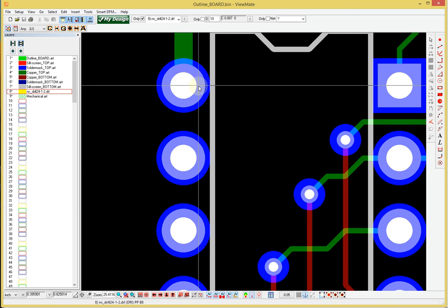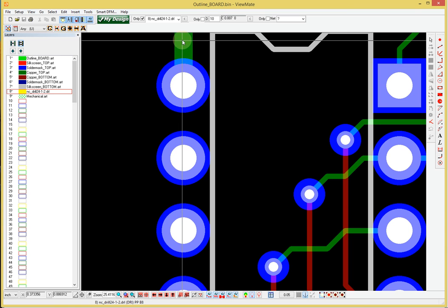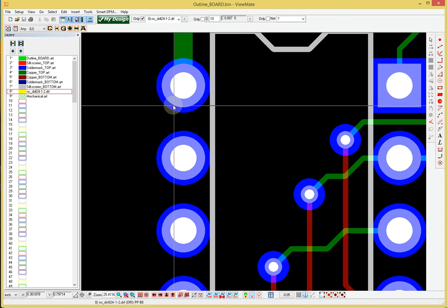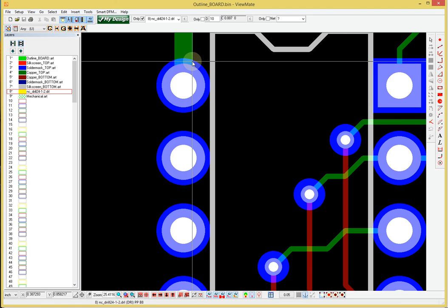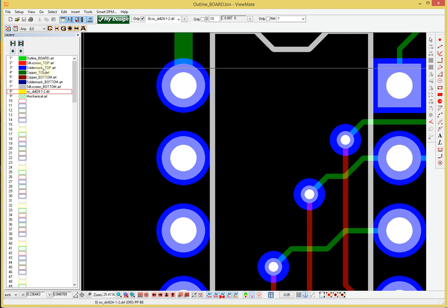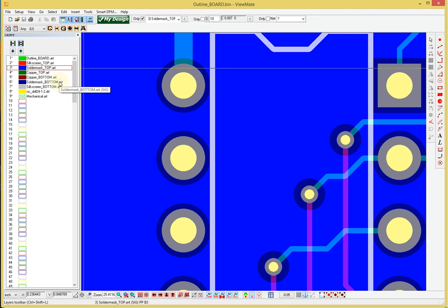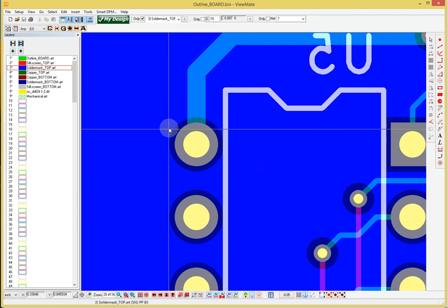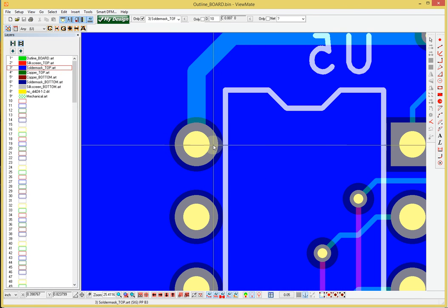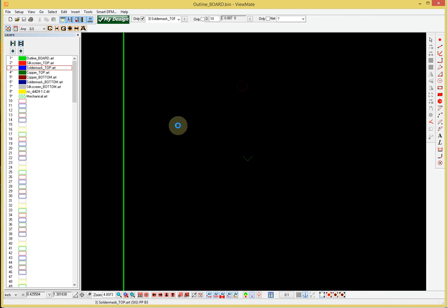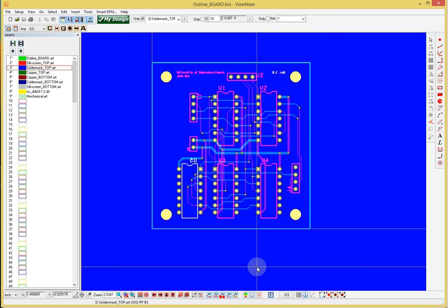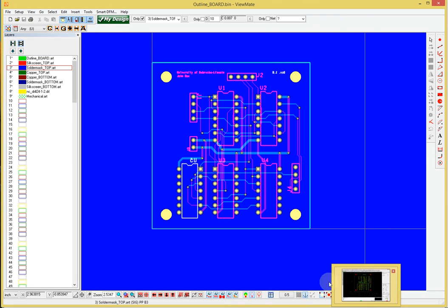Then we have the copper pad around it that is connected to the trace, and some clearance between the pad and the solder mask that protects your board. Let me reverse that to make the point clear. The solder mask protects everything else except where we actually need contact with the copper. So there it is for you, all of these stages.